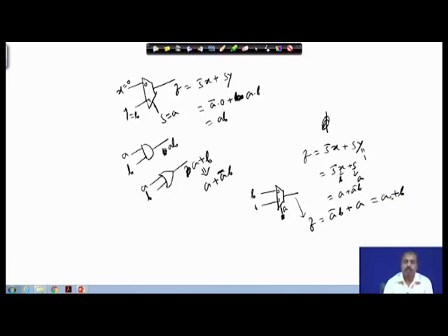Can I get an inverter? So, if I have got this function, okay. Now this S, so this is 0 and this is 1. You see that when S is 0, the output should be 1. So, I take the multiplexer, and on the 0 input I connect 1 and on the 1 input I connect 0.